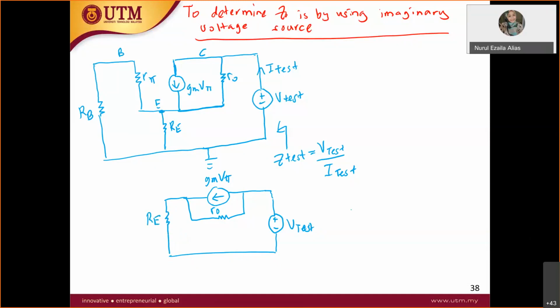Okay, you have RE, and after that, at the point of RE, you have plus minus V pi, and then you have R pi. R pi straight away connects to RB, which is in series. So this is R pi, where this point RE is connected to the negative V pi here. So this is negative first, and then this is plus V pi.